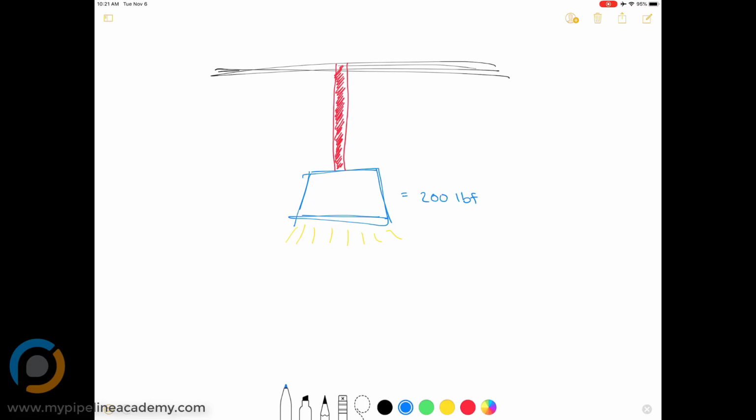But how would one go about calculating the weight of the rod when we don't even know the dimensions of the rod yet? Mm-hmm. So they'll have to do the equation again at the end, right? Like plugging it in. Yeah, there would be some iteration at the end. If you end up with a really thick, heavy aluminum rod, then yeah, you'd have to go through some iteration and add that back into the equation. But I'm pretty sure that this rod isn't going to end up being too thick anyway. So we can assume that the weight of the rod is negligible for this equation. Sounds good.